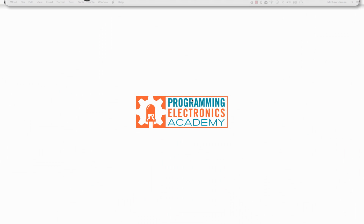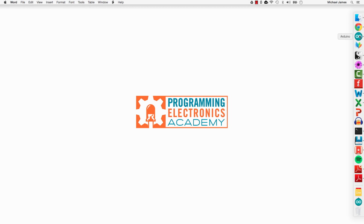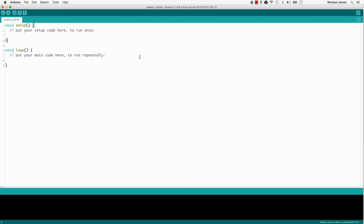So let's go ahead and open up the Arduino Integrated Development Environment. Here's the Arduino icon. And again, this is just the Arduino program. So when you click that icon, this opens up the IDE. Now the first thing we're going to talk about is selecting the correct board and serial port for your Arduino. So basically what we're going to do is let the Integrated Development Environment know what Arduino board you're using.